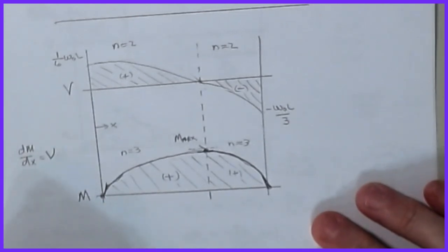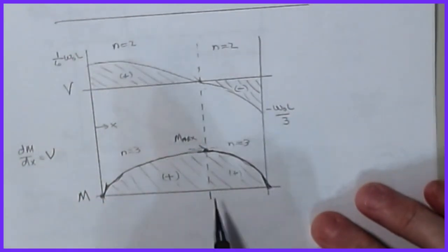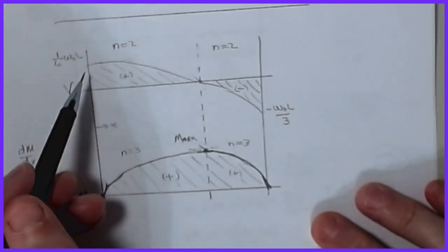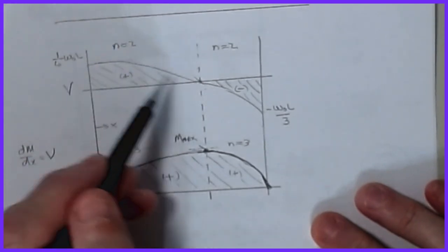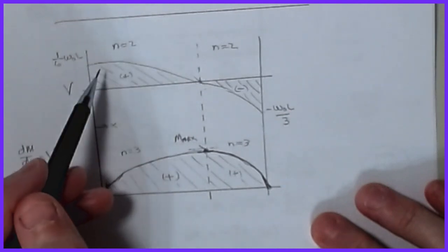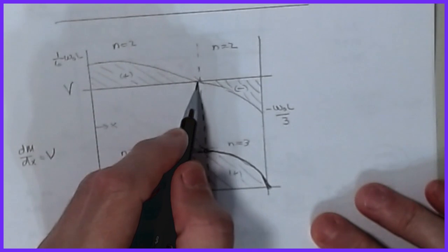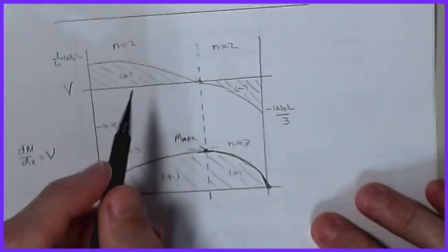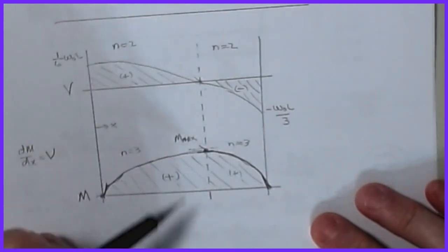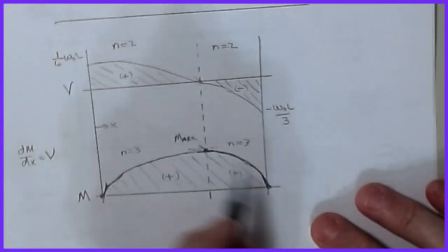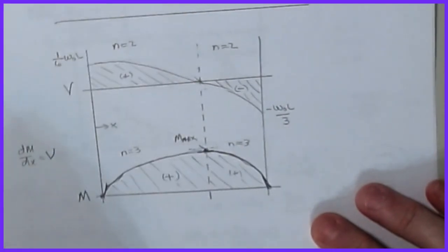So that's how you handle the distributed loads. There's really no easy way to go back and figure out the equations or these areas. In some special cases, you can use those tables in the back of your textbooks that have parabolic spandrels, but you have to be really careful about the boundary conditions. In my opinion, it's easier to go back to the generalized equations that always work, generate what the picture looks like, and figure out the maximum value accordingly.